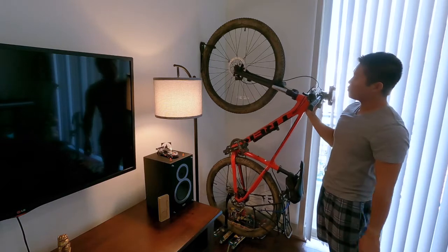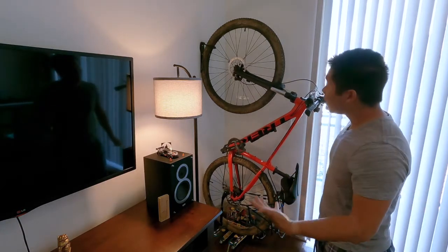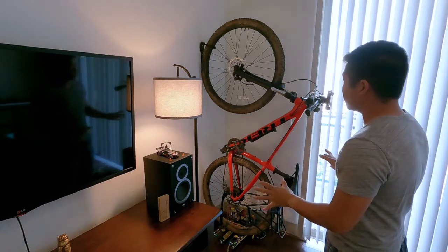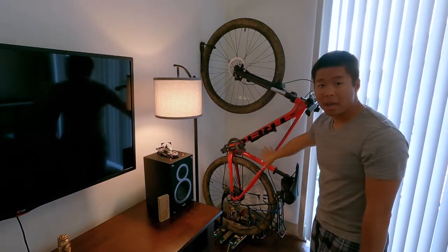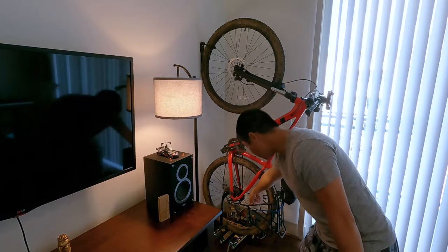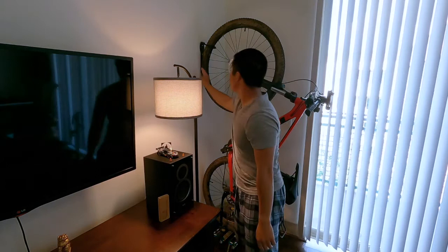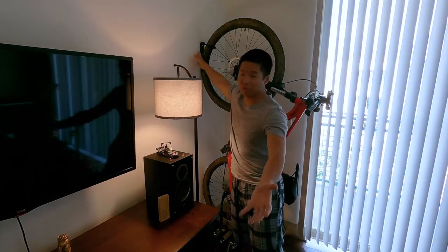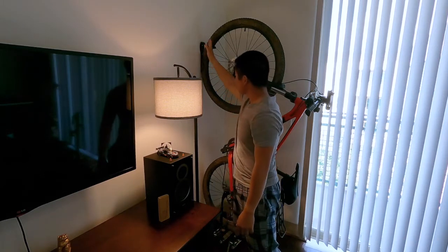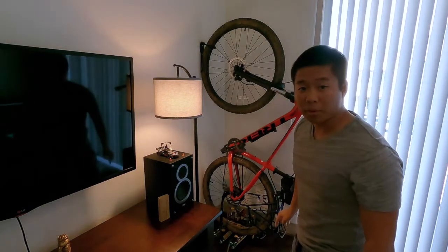Upon first sight, you'd say, well, this system doesn't really look like it should work, right? But if we look deeper into it, we find out that this system actually makes a lot of sense. So the first thing we need to look at is what is going on. Well, first, the bike has some weight, and the weight is directed downward. What's counteracting that weight is a bicycle holder that is attached to the wall and studs. If it weren't, it would just rip out the sheetrock. So this thing supports a vertical force going upward.